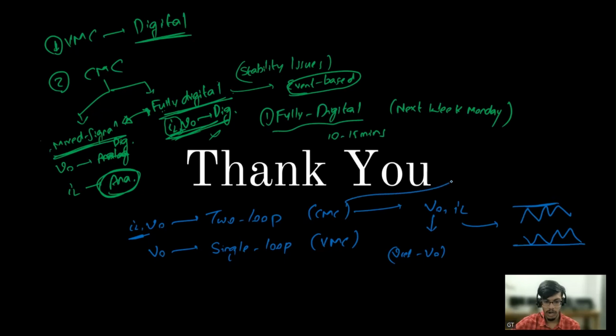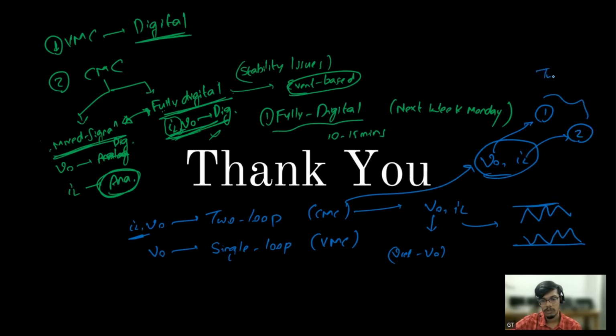So in current mode control, I have flexibility to control V0 as well as I0 independently. So as you have to control this, this needs one loop, this needs another loop. So it is a two loop control, and it cannot be used in a single loop. Single loop you can use when this I reference is there, right? So I reference is coming from the outer loop, right?